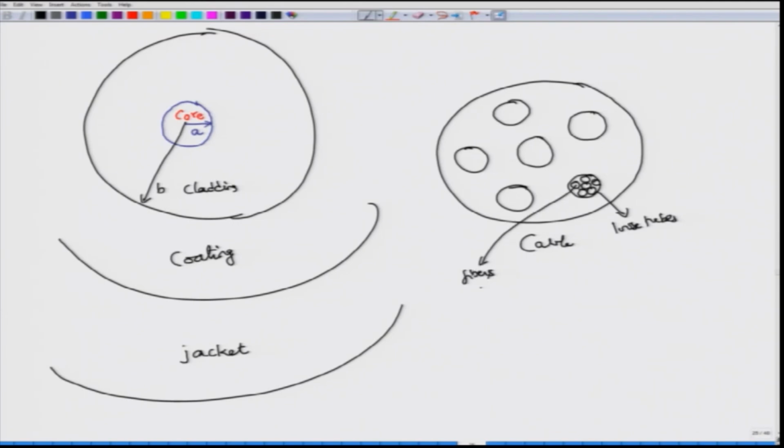Here these fibers just have a core and a cladding. Okay. They do not normally come with the coating, and these loose tubes are also differently colored for visual inspection later on, but this is how an optical fiber cable looks. As I have told you, this is not the only cable design, there are many designs that are possible, and this central member, okay, does not really carry anything.